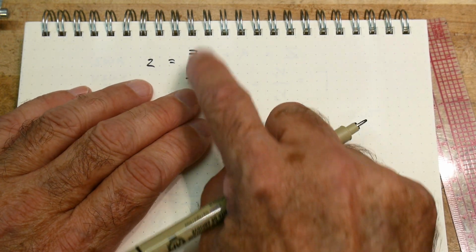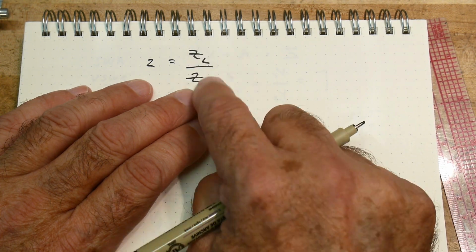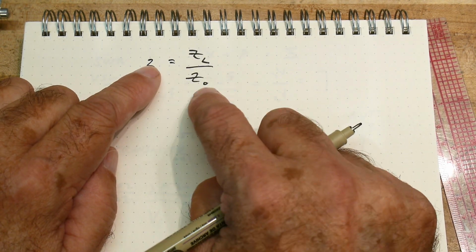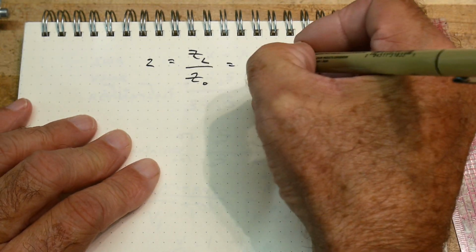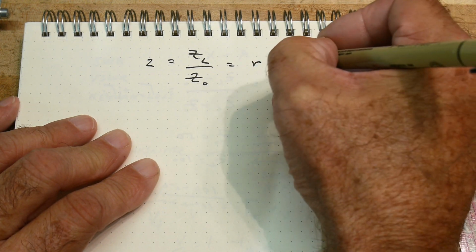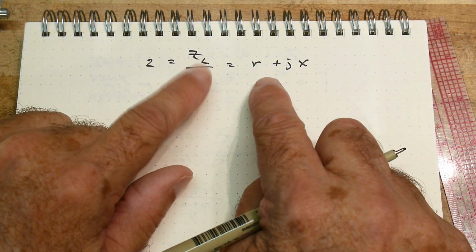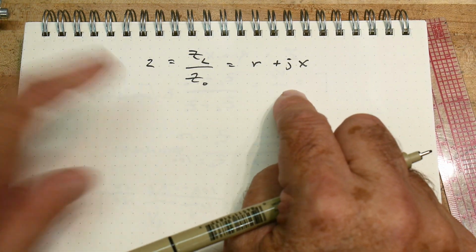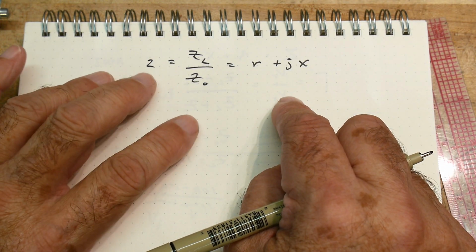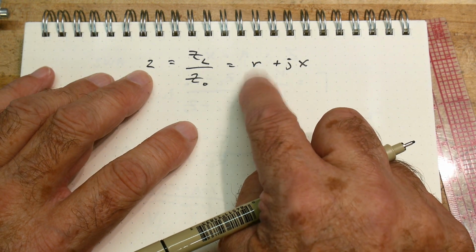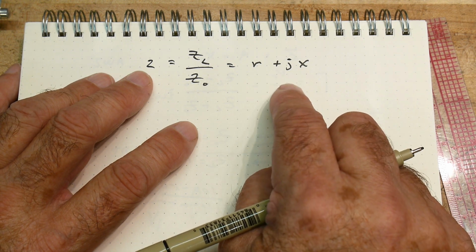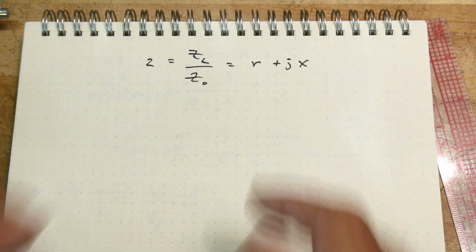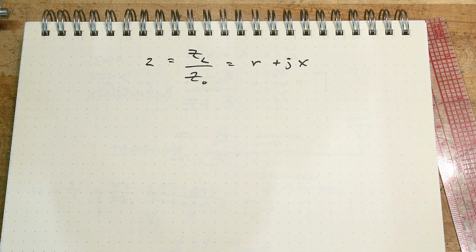All right, so if your impedances match, then your little z here is going to be 1, okay? And we can also say, okay, that's just like a resistor plus some reactance, okay? It's the same thing. And so we've introduced this new little variable, z, and we say that it's the resistive part you're interested in and the reactive part that you're interested in, because everything is complex, all right? All right, so if I haven't lost everybody already, I'm going to lose them now.